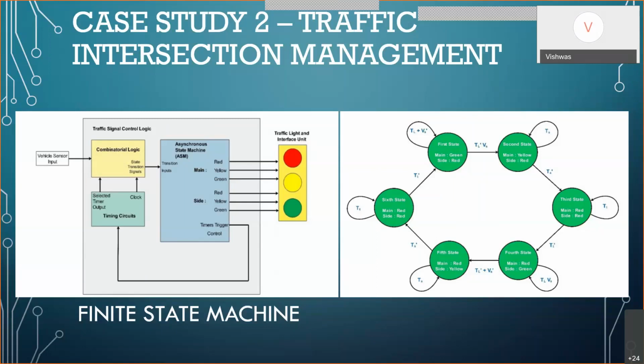So first, it's a sequence of operations repeating in a loop. This concept of finite state machine is adapted for a fixed traffic control system, where the time duration is fixed. And this works perfectly fine when the density of vehicles is normal. If there is a variable density, like one road is having less density, which will not lead to major city traffic, so it will have less traffic, whereas the other road, which is maybe the east-west road, might have more traffic, then this won't work.